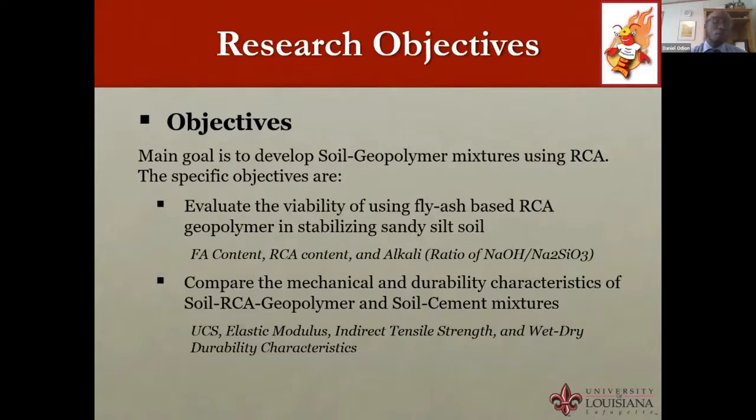The objective of this research is to evaluate the viability of using these geopolymers, which are formed from fly ash and RCA, in stabilizing sandy silt soil. The viability we're talking about here is looking at different parameters like compressive strength, tensile strength, and durability in comparison to the soil cement mixtures, which is what we presently have in the industry.